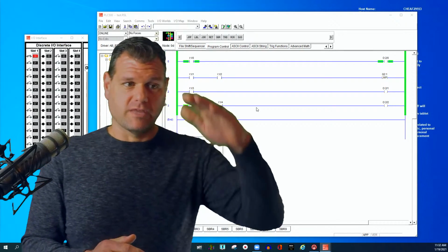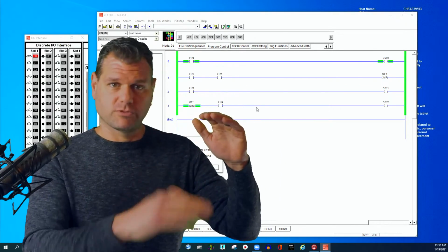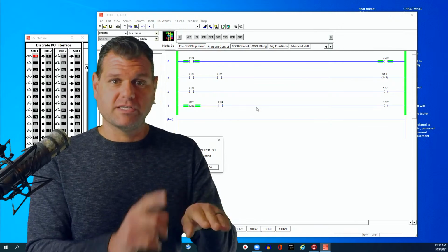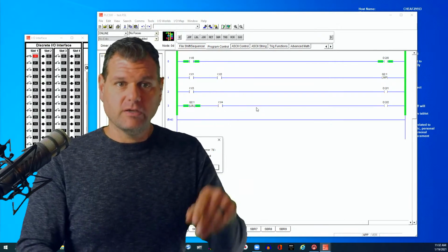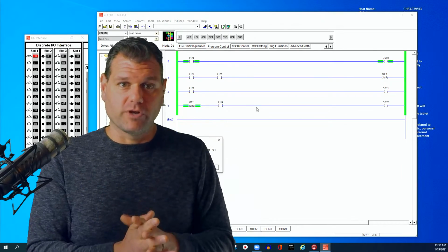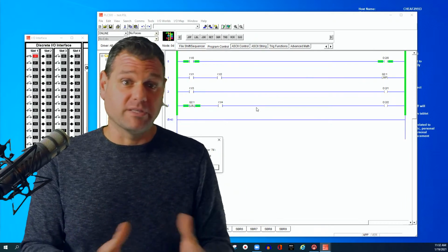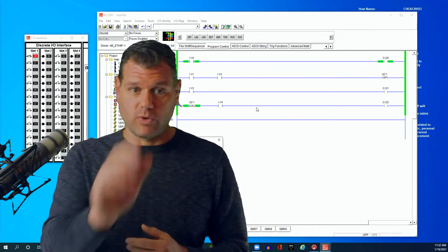So basically, let's say that we are reading rungs 1 through 20. Just read them like normal. We get to 20, it says jump to 50. It jumps to 50, and now you have completely skipped over anything between 21 and 49. So all those are just not being scanned. They're not even looked at, right? It just skips right over them.